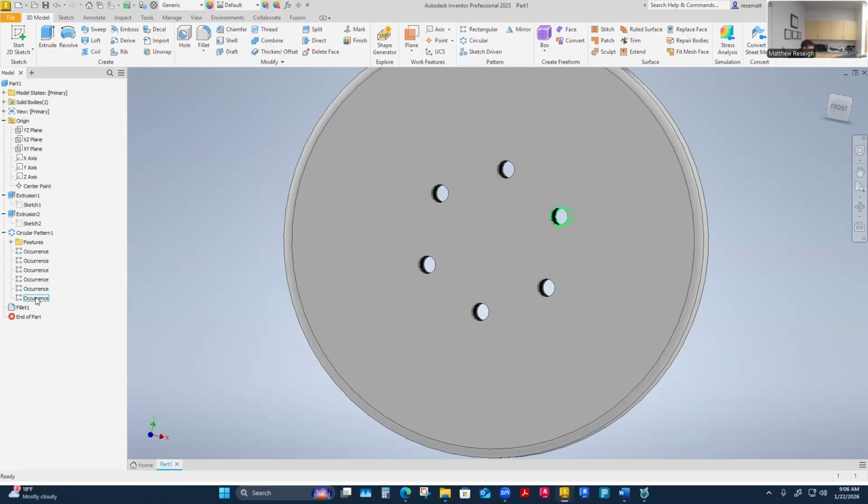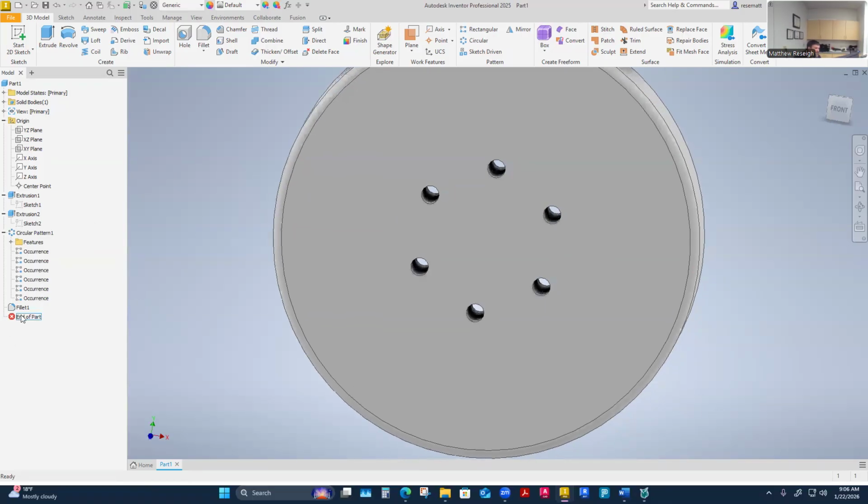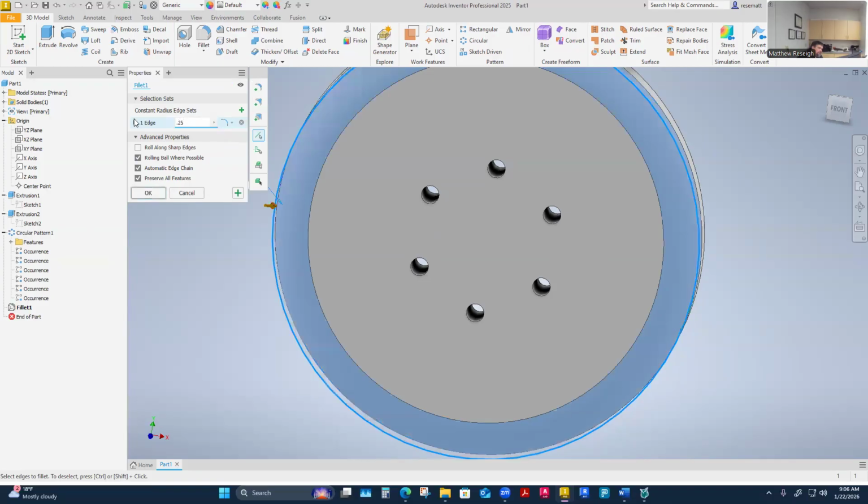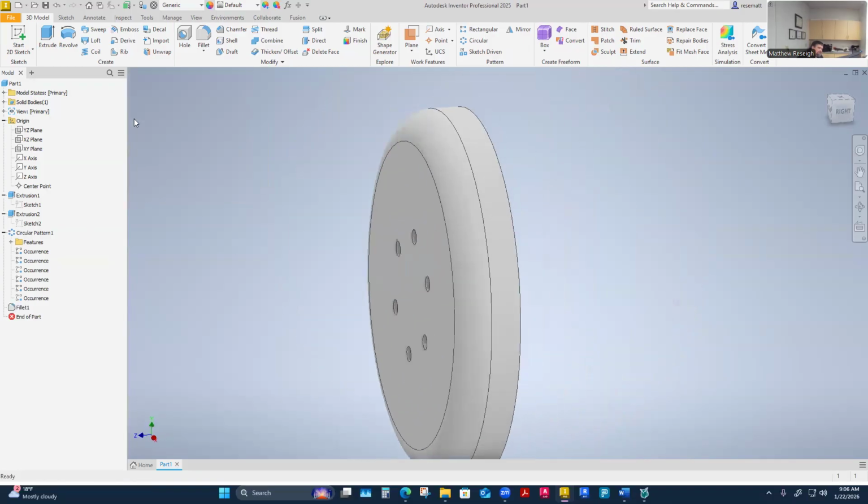I think the last thing, well, maybe there's more to it here. Let's see here. I'll just go through real quick. It has us edit the fillet to a 0.25 fillet. So that's one of the last things: go to the fillet, right click on it, edit its feature, change it from 16th to actually be a 1/4 inch fillet. Yeah, 0.25. So it's a really big fillet now.